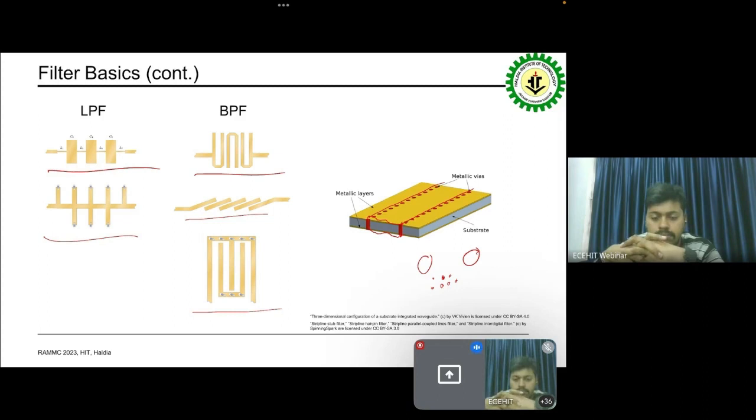You've also got a ground plane, which you can almost kind of see down here on the bottom, and then your top conductor plane, which overlays the entire substrate. So in effect, these sandwiching conductive planes form those top and bottom walls of your waveguide.